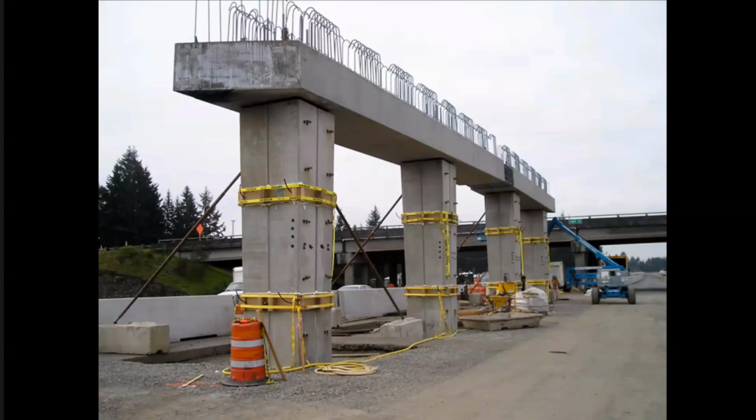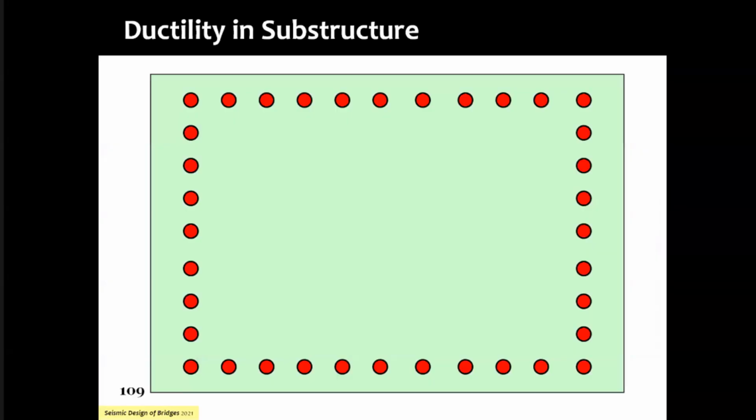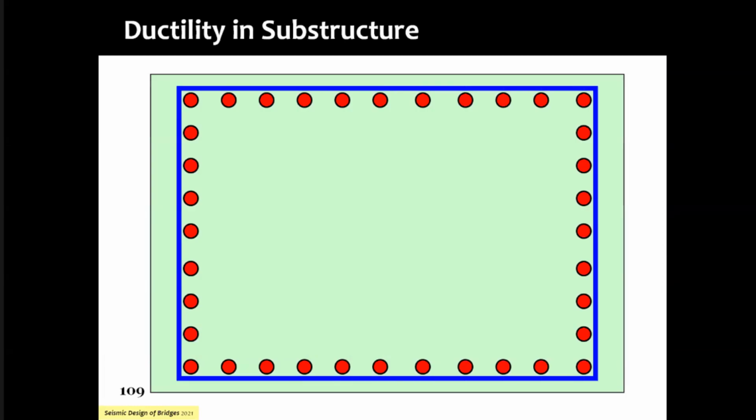And that is why whenever I see a picture like this, I feel heartening. It's heartening to see a square, near square cross section being used. One issue that is coming up in wall piers is the shear failure. It has to fail in shear only, the wall pier. But then the question is, how do you really make it fail in shear?